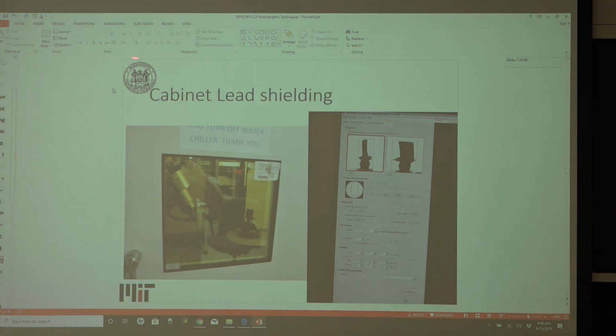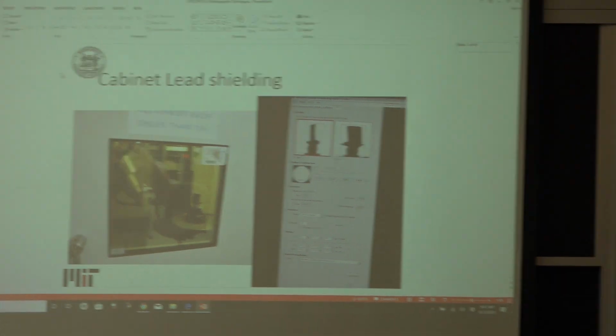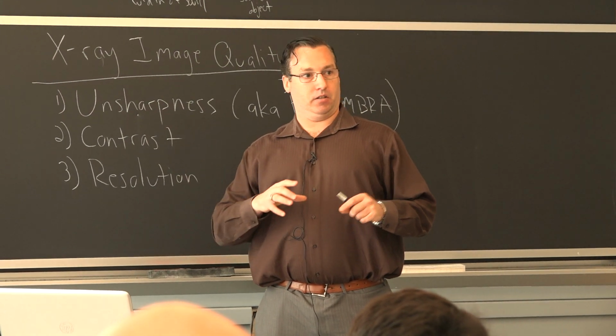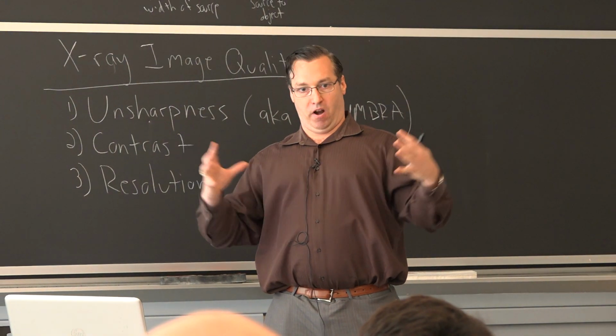So when you set up the sample, what you want to do is actually saturate the part that you want to inspect. By saturating it, you're going to be sure that when it renders it, you're not going to have any dropped 2D scans. The dropped 2D slices are when you don't fully penetrate the sample and the x-rays don't appear in the rendering.